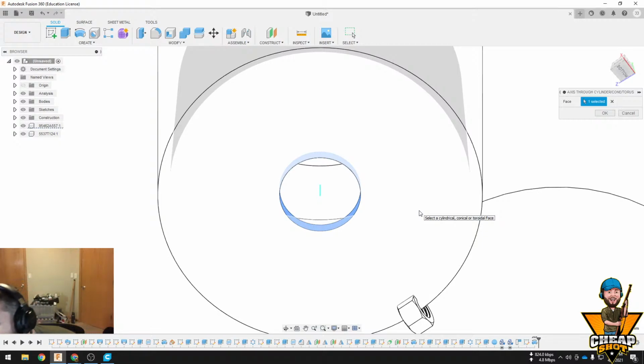How do you personally account for shrinkage when printing PLA? Is there a rule of thumb, or just go by trial and error to get the dimensions you need? So, what are you shrinking? Are you referring to the holes that I'm talking about? Because you've got to remember 3D printers don't like holes. They don't like round things. PLA, it's not necessarily going to shrink on you. There are videos on it. I think they account for about 2%. But I've never really had an issue with shrinkage. So what personally are you encountering where you're seeing this shrinkage?